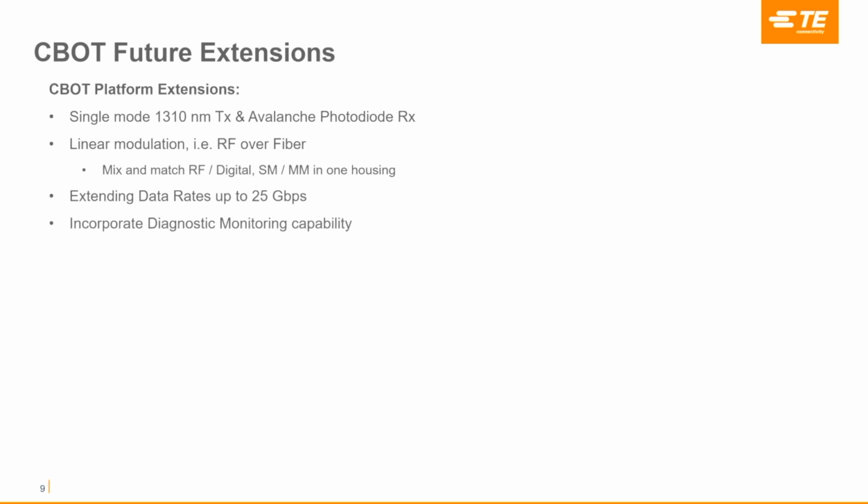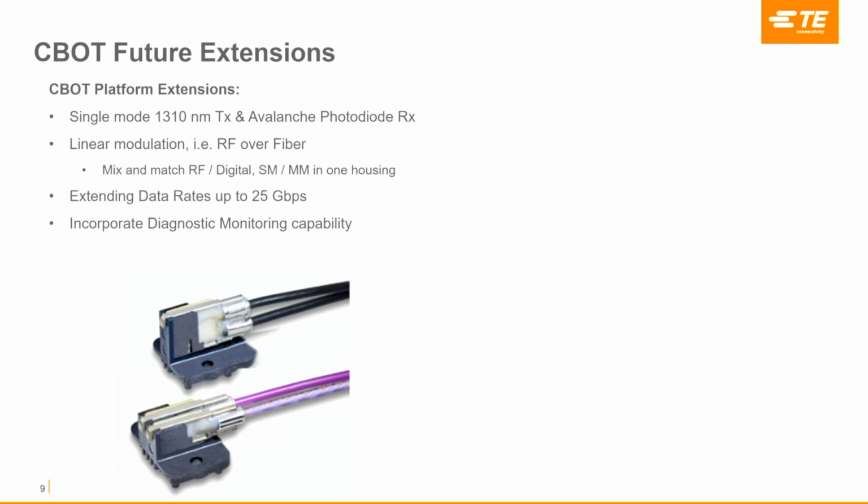If you remember the little do not include sign from that SFP at the beginning of the talk, digital diagnostics is important to folks, all right? They want to know what the health of their transceivers are. So we've looked at how do we incorporate that into this chiclet-based transceiver, and as it turns out, RT2 is forgiving, so that in the lower height module, we've got an extra differential pair on that 7-pin array that's the standard RT2 footprint, so we can put the I2C interface right there, and we have identified small enough microcontrollers that have enough memory in them that can literally make this look like part of an SFP module.